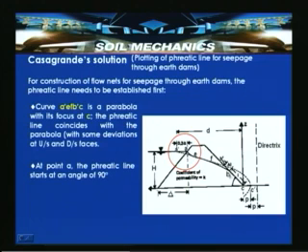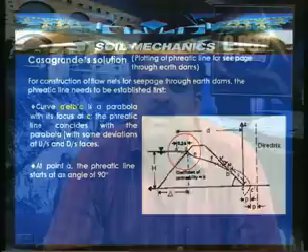We will come to this because some observations have shown that when the beta angle is greater than 30 degrees, there are some deviations. So Casagrande has given some methodology on how exactly to locate BB dash and BC in case beta is more than 30 degrees.